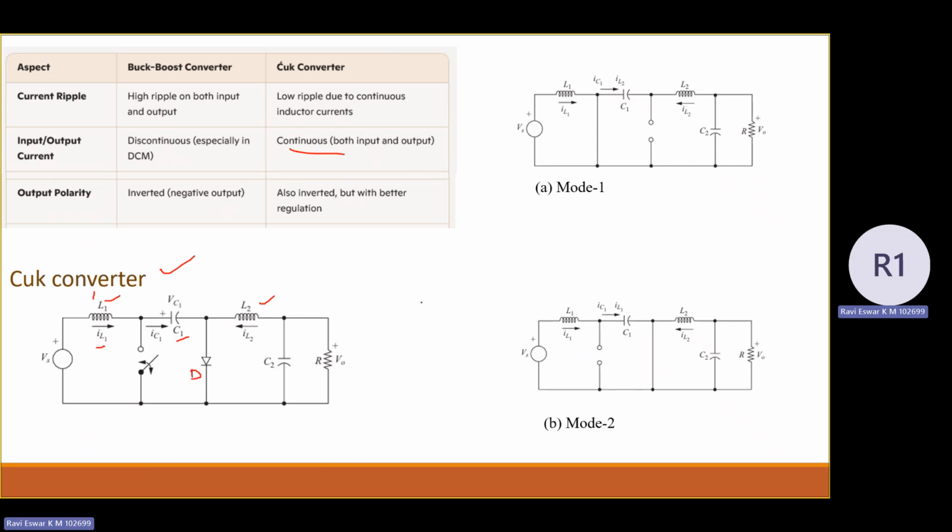Analyze the converter when the inductor is in charging condition. Let us name it as mode 1. In a basic manner, the switch is closed. When the switch is closed, the inductor is going to be in charging state. This is applicable for the basic converters, which is well cited in the literature. So try to apply KVL and KCL, and check the currents and voltages.